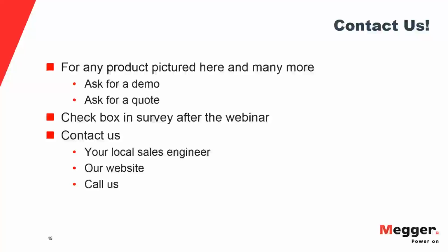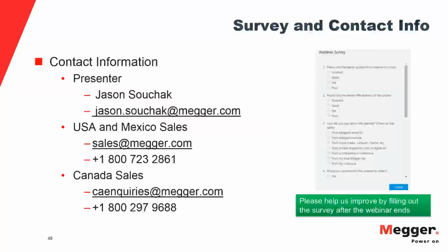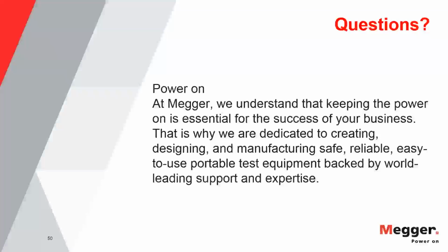Okay, hello everybody. So this is Robert speaking. What Jason presented on is mostly and specifically for offline cable testing, and that has to do with the special role that the cable has in the overall power system. The way it's used is it is the only distributed component. Most of the other components are localized and specifically located in substations. So this type of offline test is mainly an acceptance test, and partially a type test in the factory.